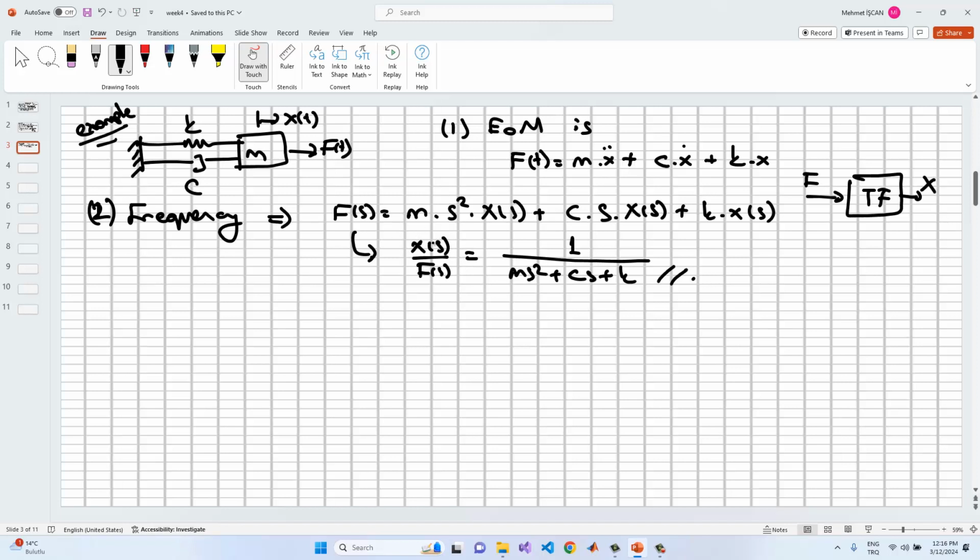And so if we turn this X into the velocity, we should define another transfer function in here, V(s), just like this one, s over m s squared plus c s plus k, right? Why do we need to add the s in here? Yes, it's a derivative operator in Laplace transformation, and so we multiply this value by s. And so we have two transfer functions in here in frequency domain, but we can also utilize another domain in order to analyze these terms.